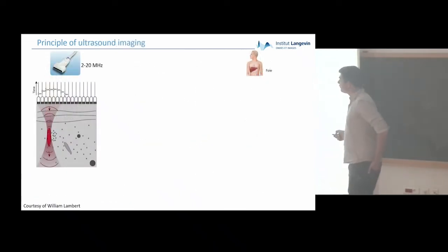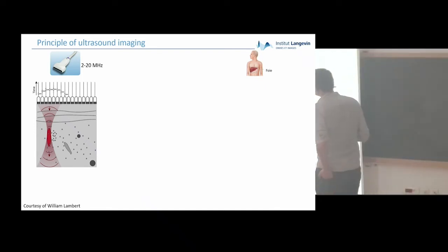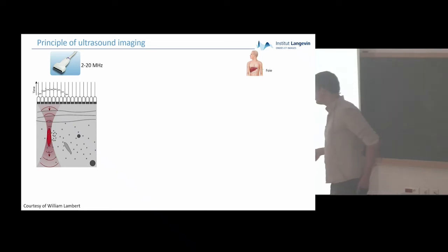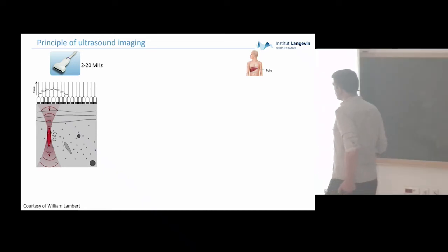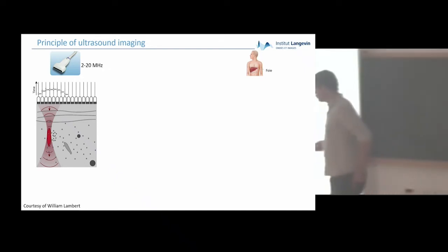So now, what happens when people in the acoustic community later started to use this wonderful ultrasonic probe that is made of an array of piezoelectric transducers? Then you do not have to scan your probe, but you can use electronic delays applied to each piezoelectric transducer in order to focus whatever you like in the medium.